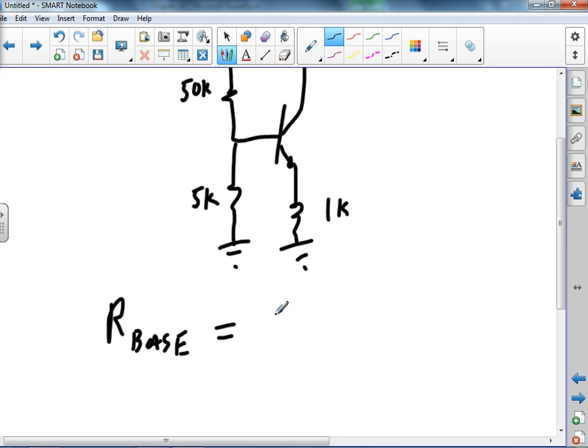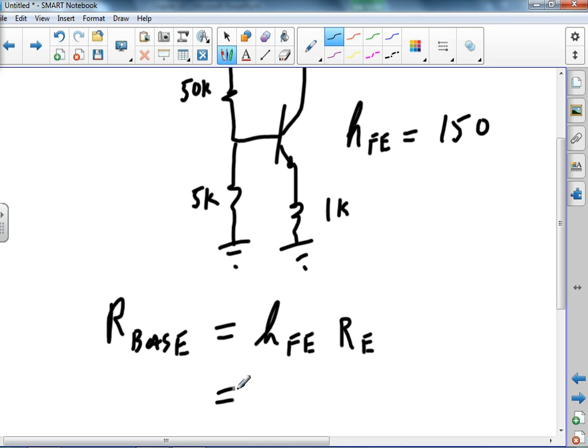So all I need to do is find that guy times RE. Okay, now, did they bother to tell us? Oh, yes, they did. So my beta is 150. So 150 times 1K, also known as 150K ohms.